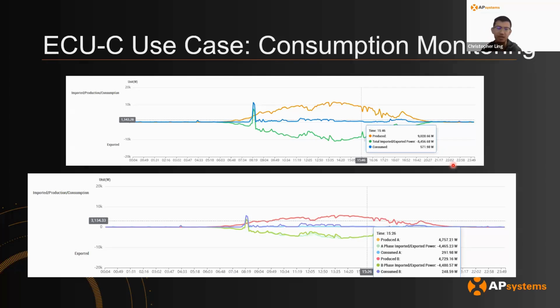In our experience, a split phase export controlled system tends to be over aggressive in reducing the power of the solar system. So it is possible, but if the system is not balanced for a split phase system, it may over limit the solar production.